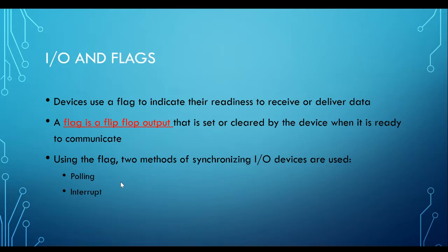And then we also have this thing called polling or interrupt. How does the CPU check the status of the device? You have two methods, called polling or interrupt. When you poll, you normally use the main program to poll. In the main program, you will check probably every round of the main program. But interrupt is free. It frees the main program to do other stuff. So in terms of efficiency, power efficiency, interrupt would be much better.